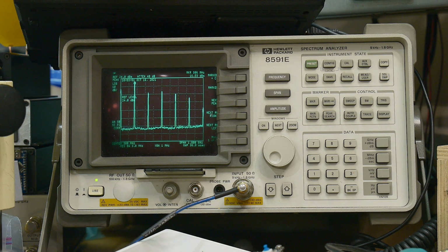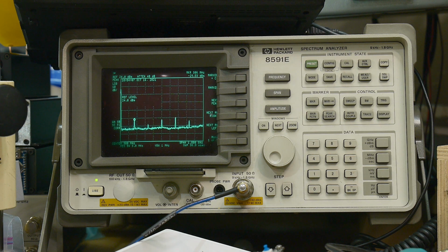In fact, I think I'll do that just for the sake of making sure that you do it in your testing. Plus 16 is just very high. So I'm going to go ahead and put a 20 dB pad on the output to make sure that we don't destroy anything, just in case it decides to go up from here. Safety first, safety third, whatever you want to say.